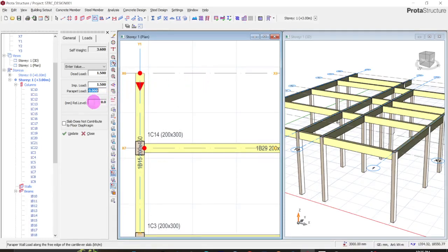So if you work out the unit weight and then multiply by the surface area, in most cases you find that it will come to 9.8 to 10.8 kilonewton per square meter. So you have to add this unit here.